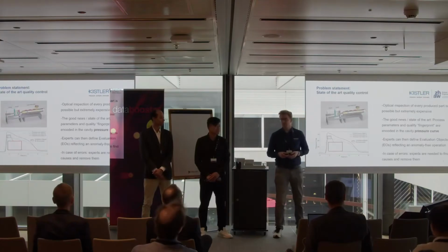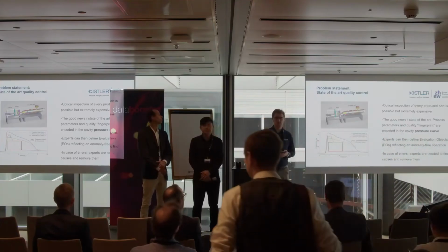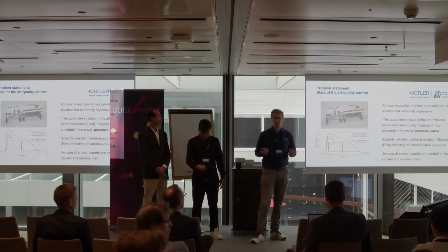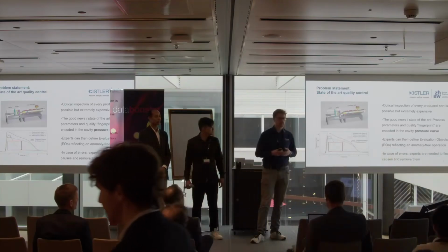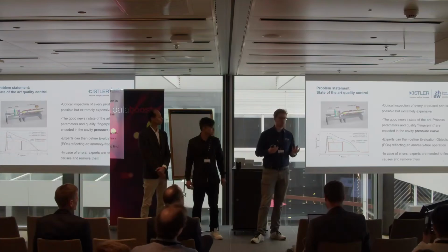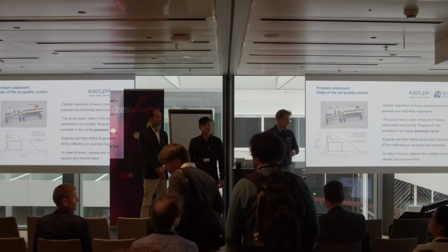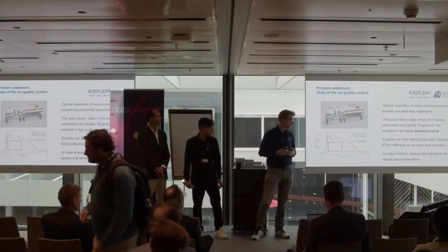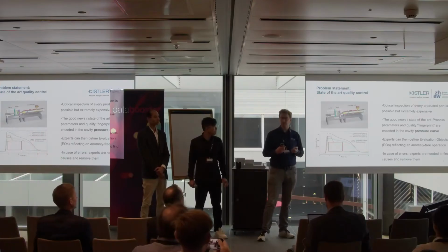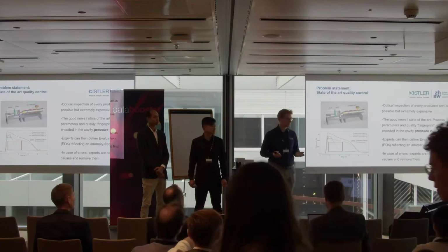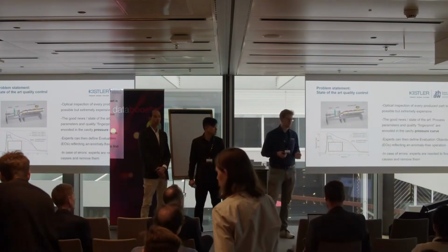All right, so let's look at the business context. Injection molding is, very briefly, a process where we have molten plastic, which is injected into a cooler mold. Heat is transferred from the molten plastic to the cooler mold, and the phase changes, and the solid part ultimately is ejected. And good news is our sensor technology from Kistler's side enables us to monitor the cavity pressure inside the mold, which is the quantity that can fingerprint the process and encodes a lot of information on it.